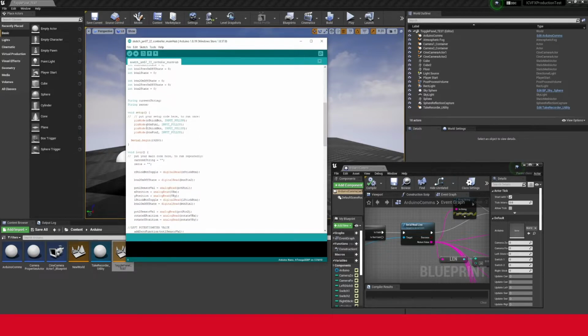So we initialize each of the buttons in here, the joystick button and the extra buttons, and we also have this set to a baud rate of 19,200. I find that 19,200 works really well with quite fast scenes, or scenes with a high frame rate.